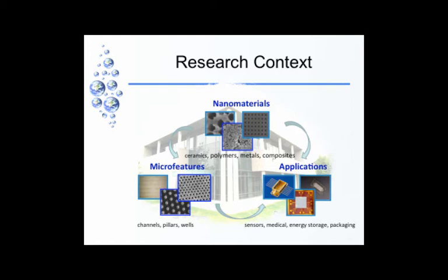And the membranes that are used for filtering are made by a combination of powder and polymer: cellulose nanoparticles in a membrane, in a polysulfone matrix. Mainly, the cellulose nanoparticles are high aspect ratio. They're long. They're about 20 to 50 nanometers in diameter and about half micron to 1 micron in length. So they're needle-like. They're also hydrophilic and they're biocompatible. When we put this in a membrane, the membrane becomes stiff.